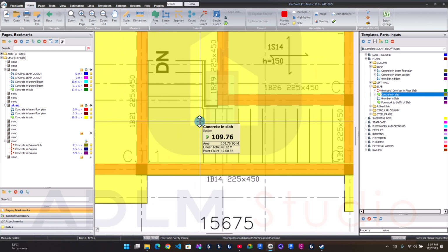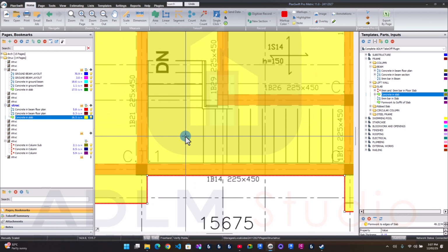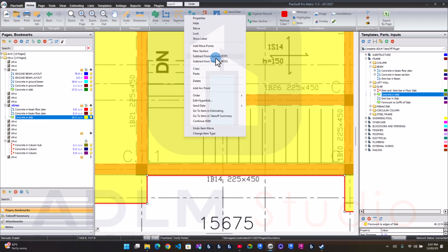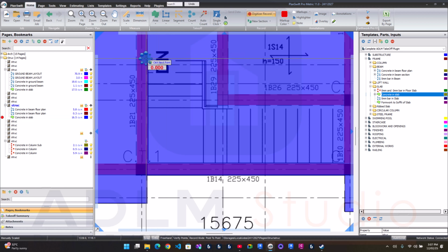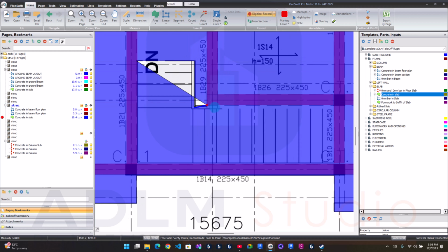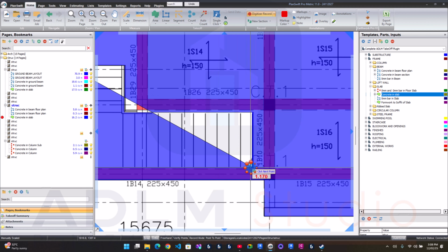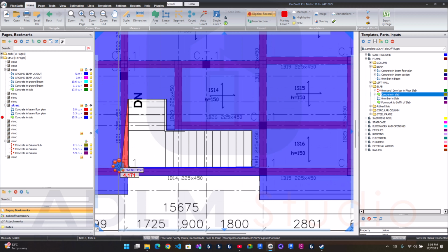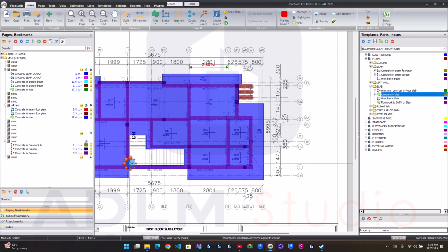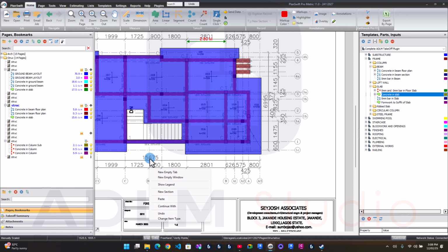So at this point here, let's deduct for our staircase opening. I'll just right click on this, my takeoff here, point to point. Then I would just deduct for my staircase opening. So basically, I'm literally just translating what was in the design before.